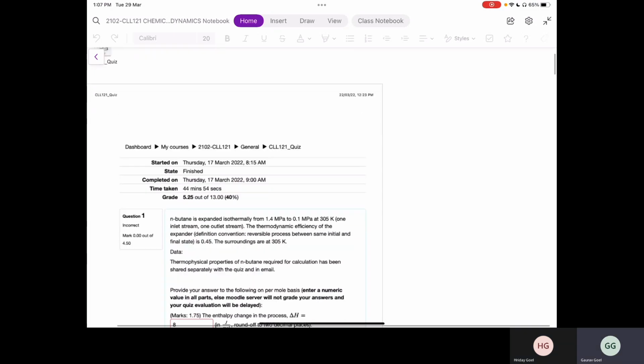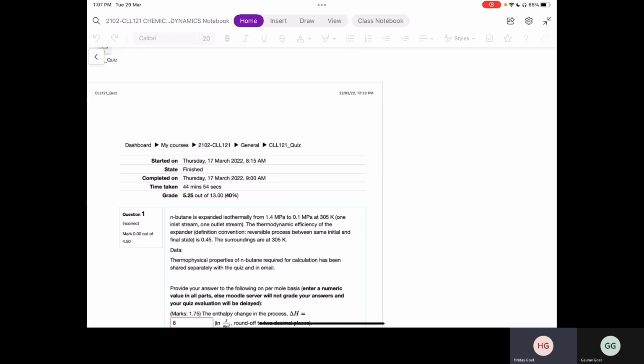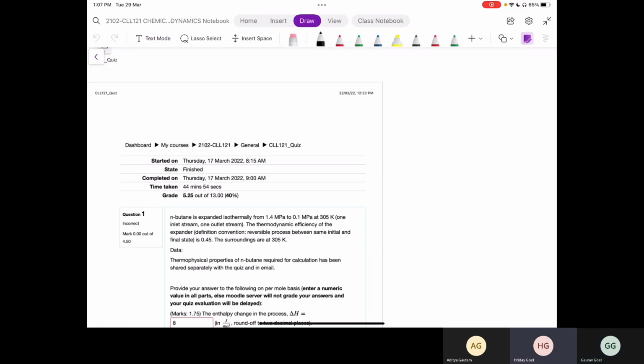So the question is isothermal expansion, right? From the given state point. So you draw the process on the PV diagram first. This is essential to understand which phases are being visited, especially the two endpoints. Where those two endpoints lie is essential to completing the problem.